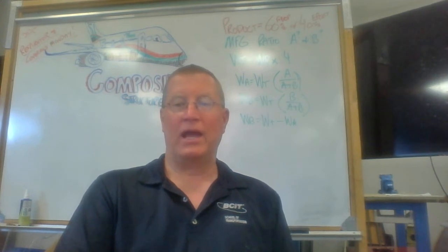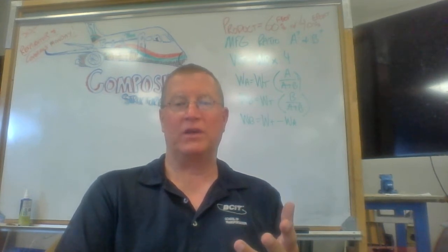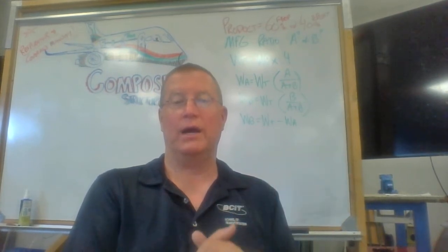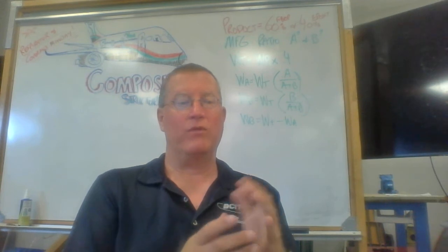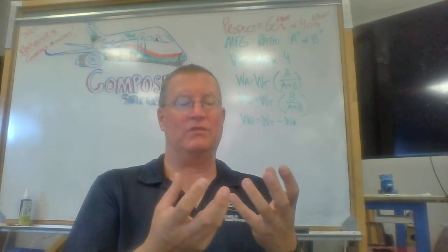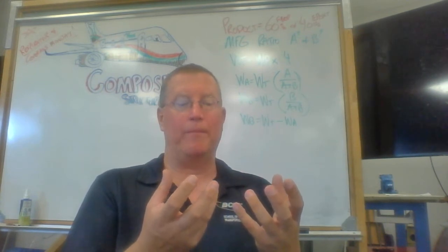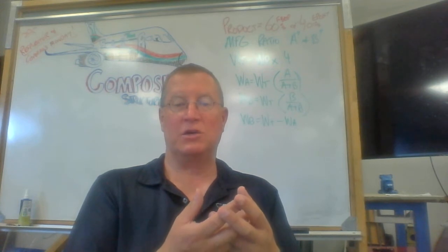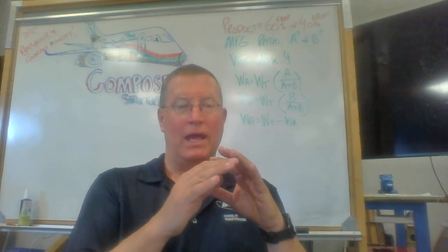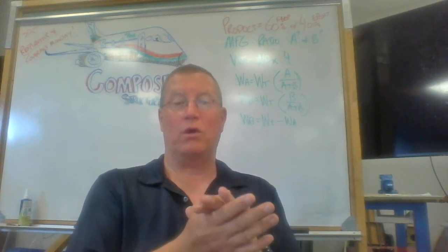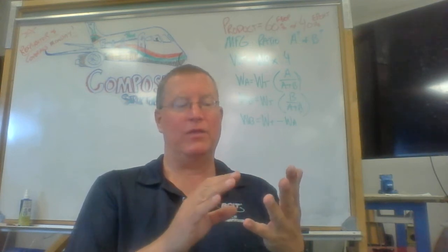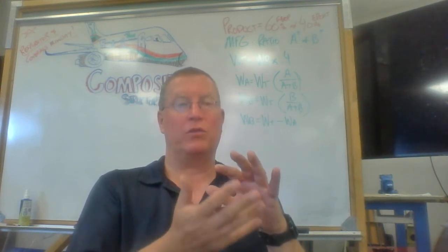We want to understand that, again, most of the mixing of epoxies is going to be done by weight. Always do it according to manufacturers. If we're doing wet layup, we've got the shelf life, which is a drop-dead date for the product in its base format. We've got pot life or working life. As soon as A and B get integrated, we're up against the clock. We've got to get the material wetted out, vacuum bagged and sealed off and ready for curing within that pot life. We don't want to have anything in the buildup that would cause a weakening.